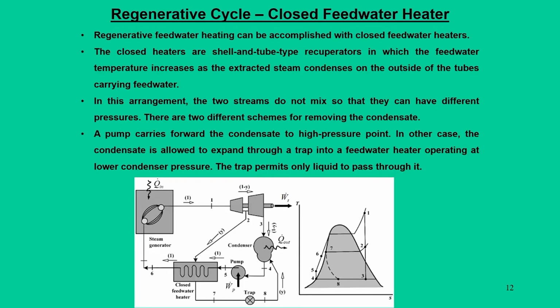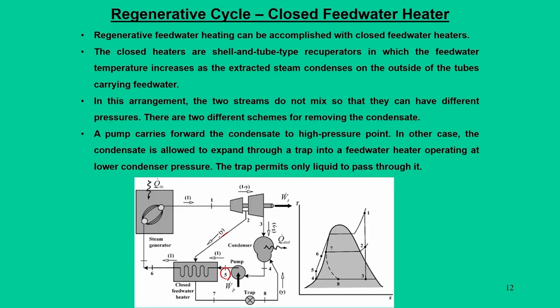But here in a closed feed water system, the main intention is that steam is not allowed to mix. So, what it means is that the y unit of steam that comes at state 2 does not mix with the condensate that comes at state 5. That means we are only tapping the heat of the steam, not the mass, which gets mixed. So, no mixing is allowed in this closed feed water system.